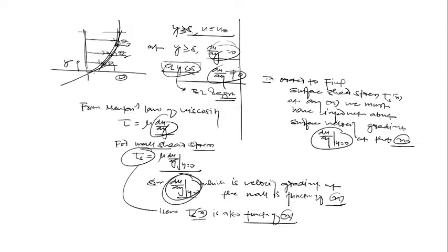So from this definition, listen, very important, from equation 1, to find out the shear stress at any given x, we must know the velocity gradient at that x. So there is an alternate approach, because you can only find this if you know the velocity profile. If you don't know the velocity profile, you can't find out the shear stress at the surface at different x.